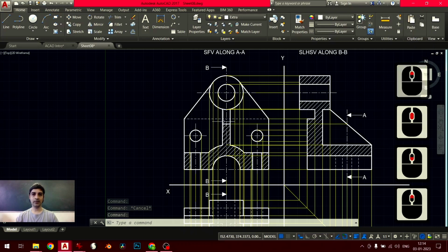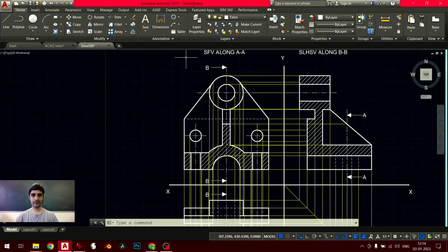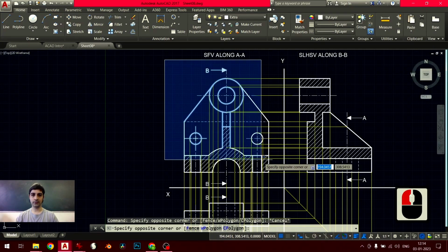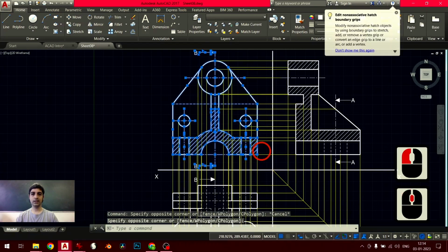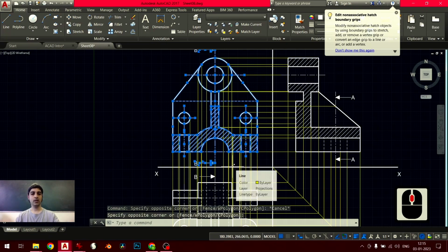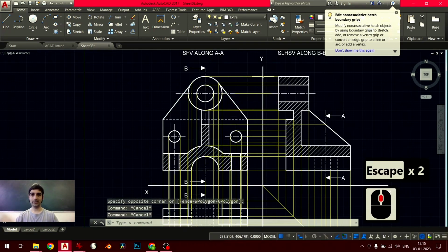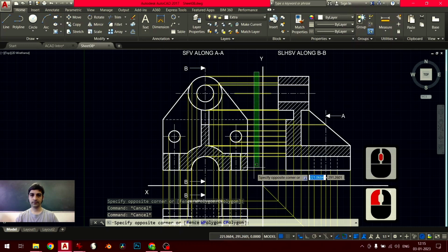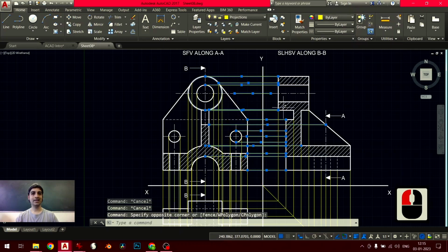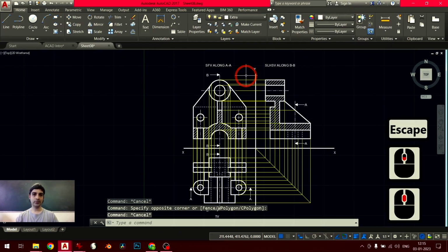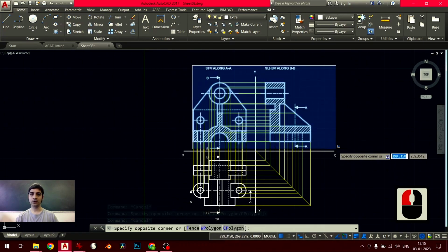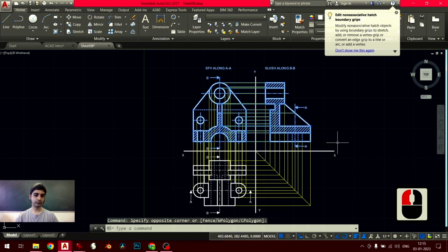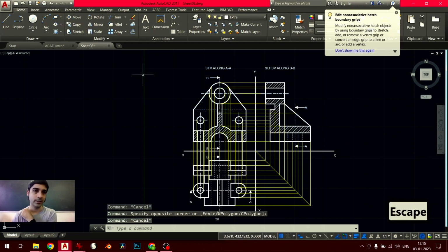So now, for example, if I want to select just this, I can make a blue box around. It did not select any of these yellow lines at all. If I want to select just these yellow lines, I can make a small green box around it. It didn't select any of these. Whereas if I tried to select these yellow lines with a blue box, I'd end up selecting a lot of additional content that I didn't want. So selection boxes, they're pretty powerful once you know how they work.